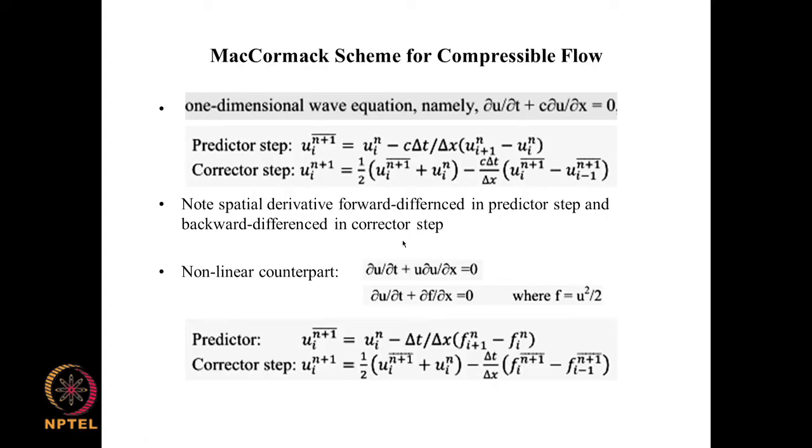Now, if you have it as a nonlinear equation, here c is constant, and what we typically have in our Navier-Stokes equation is a nonlinearity like dou u by dou t plus u dou u by dou x equal to 0. It is the same as the dou by dou x of u square term, which is where that is coming from. That can be written as u dou u in a sense with some manipulation. So, this is a nonlinear equation because u here is also being solved, and this u and dou u by dou x will make it nonlinear.